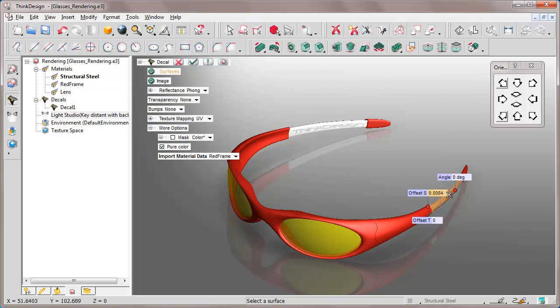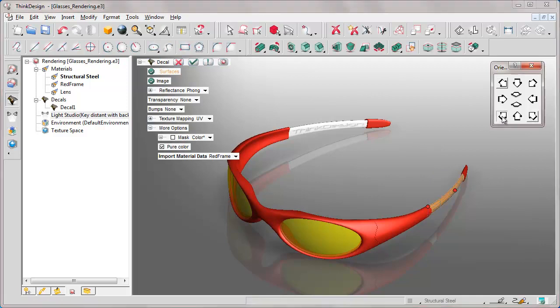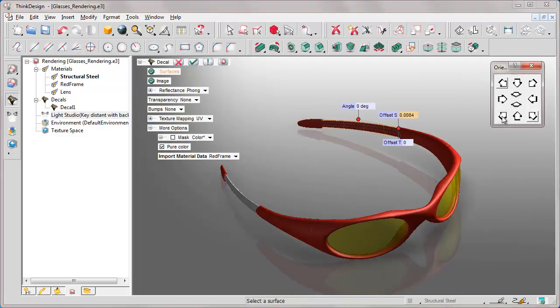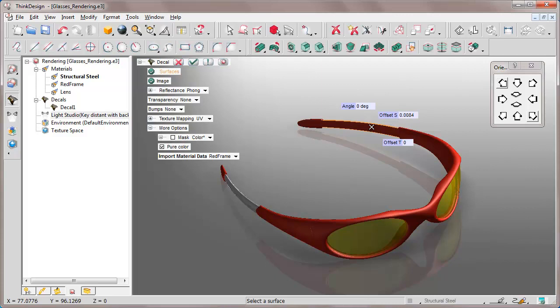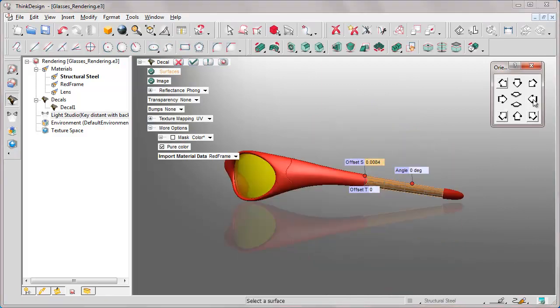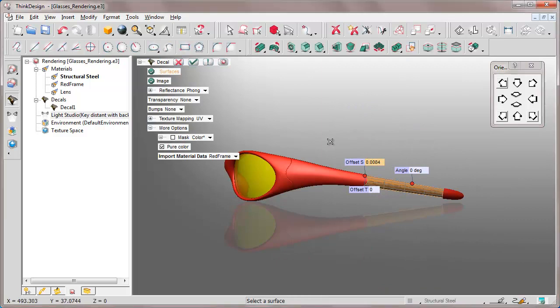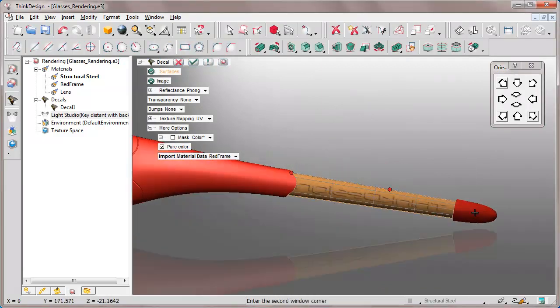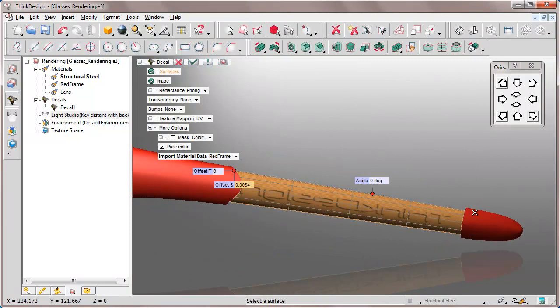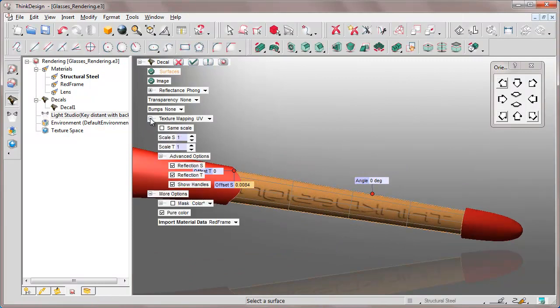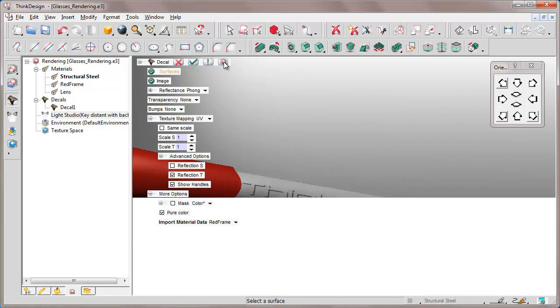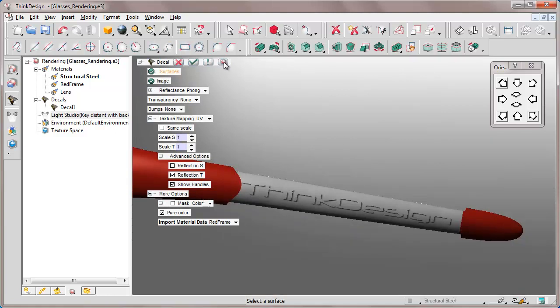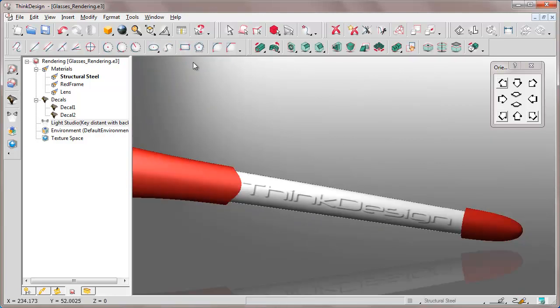We rotate the glasses, click on the internal surface, position our object, and enlarge the rod. Here as well, we are going to adjust the way the inscription appears. In this case, the mapping must be turned upside down only with respect to T. Let's make a preview. Once we are satisfied, we confirm the command.